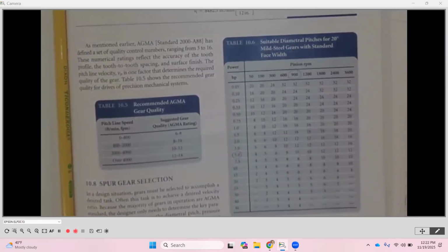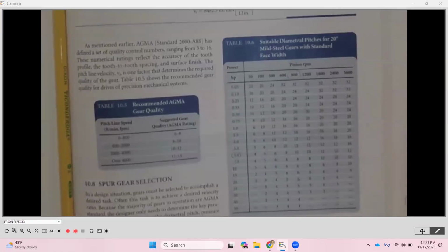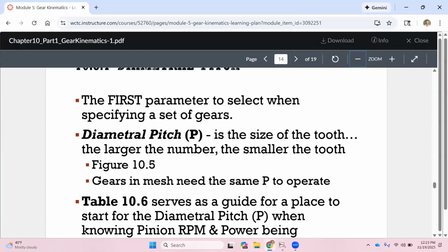Now, we're going to qualify this design and make sure that it's okay by taking it to the next steps, which, like I said, are in machine design elements. That's when we determine what the forces are here and what stresses this is going to see. Sometimes we may need to alter this number as we get further down the line in the design process. But this is just a starting point. We're not committing to the number of gear here. We're not married to it at this point, but it's a place to start our calculations. So that's where we're at in the design process. That's table 10.6.